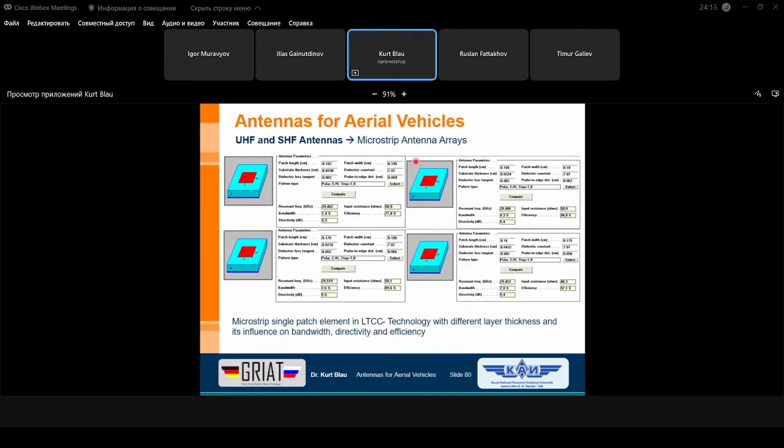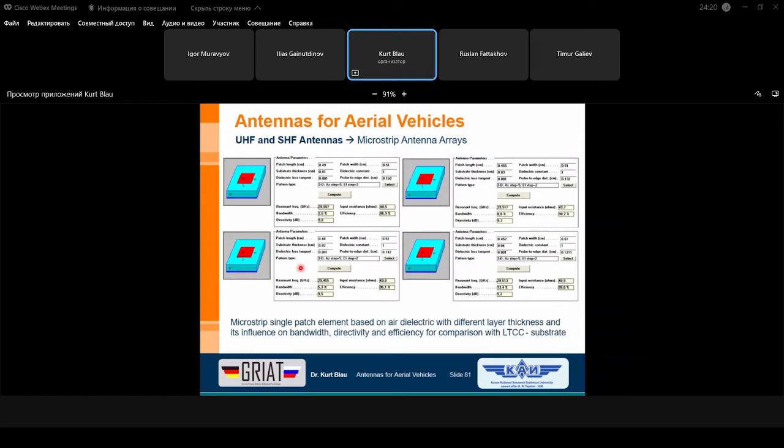This was the antenna with the high permittivity, and also the lower the permittivity, here we have air, we can also show that we have the higher bandwidth, the higher efficiency of the antenna. And it's clear it's overlaid with the thickness. Large thickness and low permittivity results in the highest bandwidth and in the highest efficiency. And this was shown in this example.